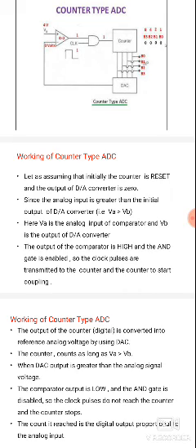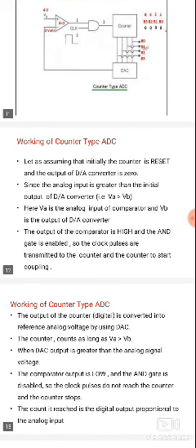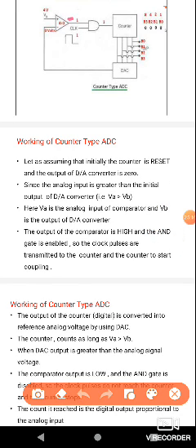Whenever the output is high, the value of VA is greater than VB. That is, the non-inverting terminal of the op-amp is higher than the inverting terminal, so the analog voltage is greater than the digital to analog converter output. Then the AND gate will be enabled. The output of the comparator is high, and high is indicated by the binary 1.